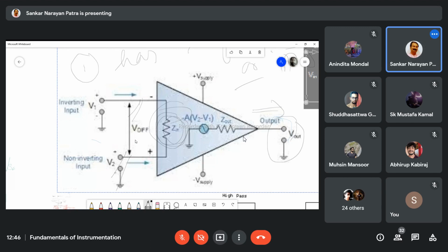Reverse bias of the collector and base region. The resistance is high there, so the heat will be I squared R t. Even with a small current, the heat will be enough to burn out the semiconductor. That's why some resistance is fed to, or connected to, the input side, and there will also be some resistance on the base side. So the total resistance of the base side is Rx.